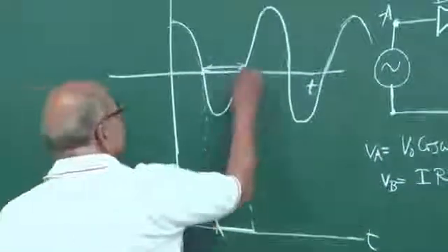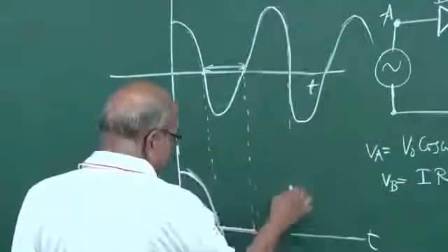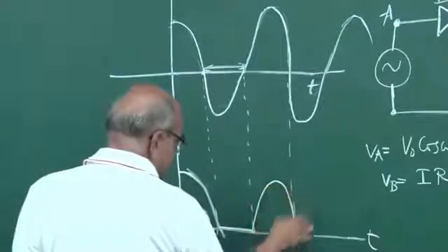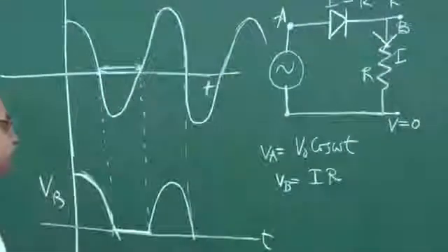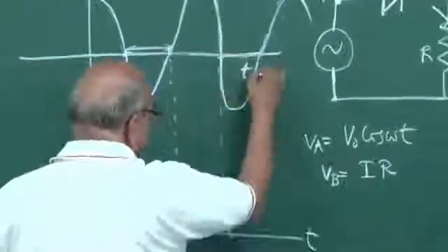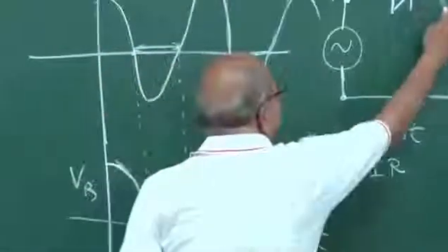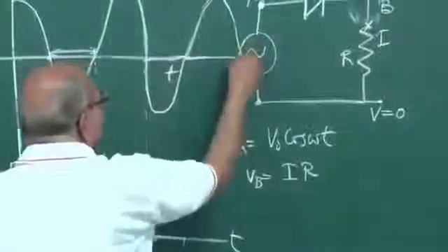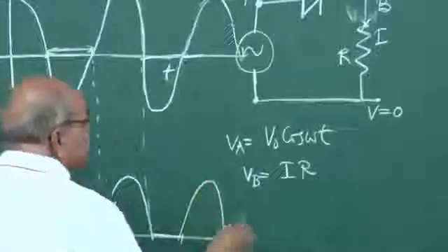And once again, this potential becomes positive. So in this period, you have a current like this or voltage like this, and the current will be here. Then in this period, you have reverse bias and the voltage is 0. There is no current, so remove this arrow. But in this period, once again, it is forward bias and you have current. So put that arrow back.